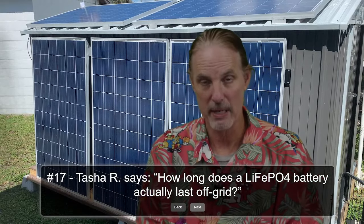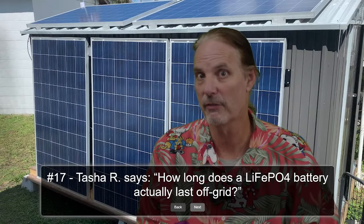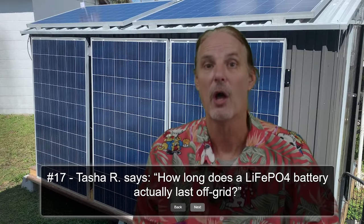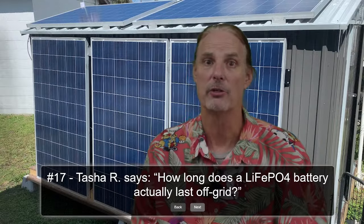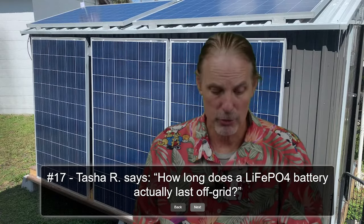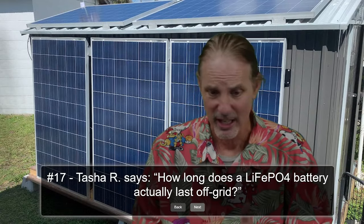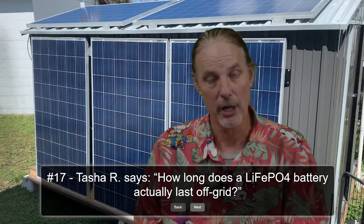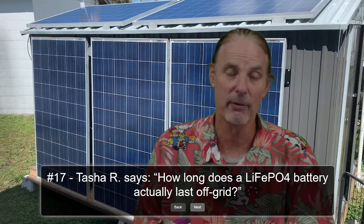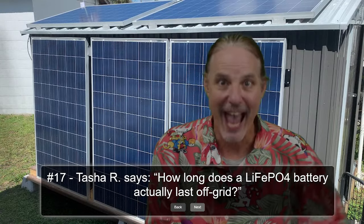In the JK BMS, you can go in and adjust the capacity of those cells. I would suggest that you go in once a year and run a capacity test. You run that battery all the way down to 0 and you charge it back up. And when it truly gets to 100%, you determine what that state of charge is. If it's a 300 amp hour battery and you only get 287 amp hours in there, set the battery size to 287 amp hours so that your state of charge can be accurate.